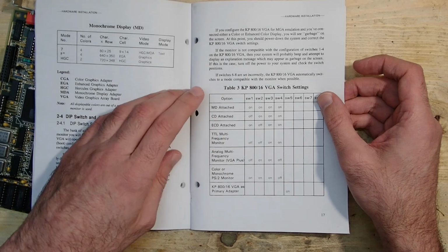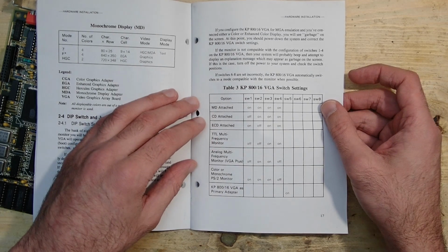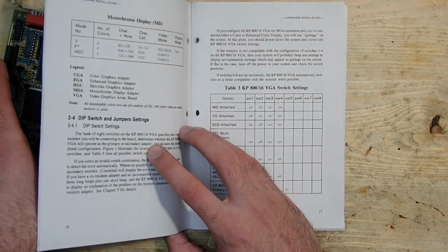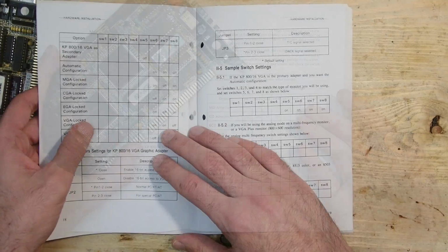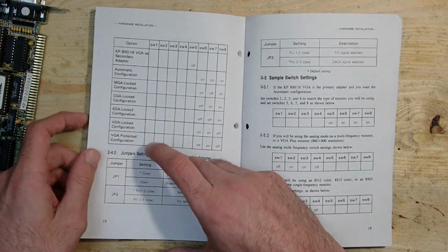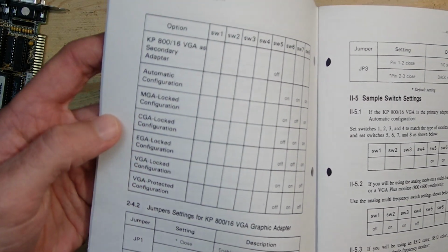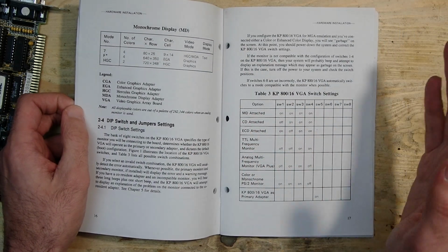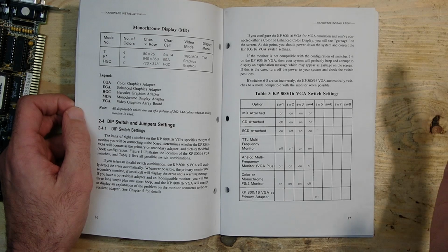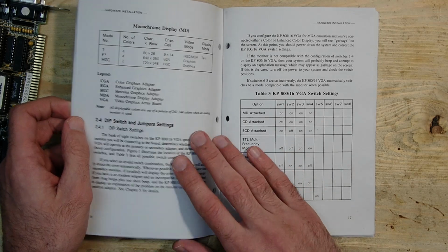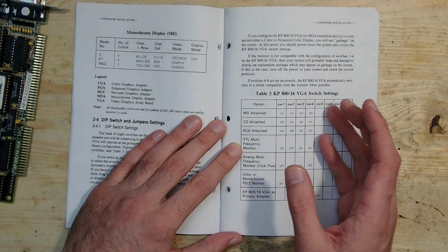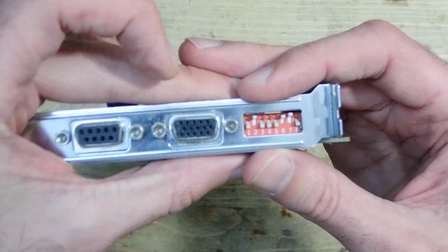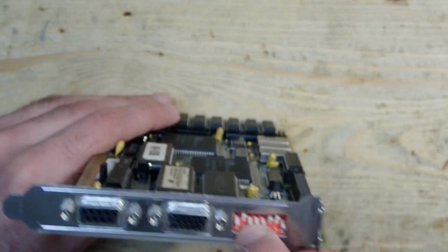This graphics card has a lot of options for the type of connected monitor. It supports digital monochrome and color displays for MDA, CGA, and EGA, but also multi-sync TTL and different analog RGB and VGA compatible displays. On the other hand, it is possible to set the graphics card in auto mode to select the video standard automatically, dependent on the display type, or to tie the video standard to a specific type. For example, it is possible to set the graphics card to EGA mode, but tell it that it is connected to a CGA compatible monitor, so it only provides 15 kHz 16 color EGA modes. This wide range of settings is something really unique. The card supports MDA, Hercules, CGA, 16 colors EGA, 64 colors EGA, 256 colors MCGA, and last but not least, VGA.